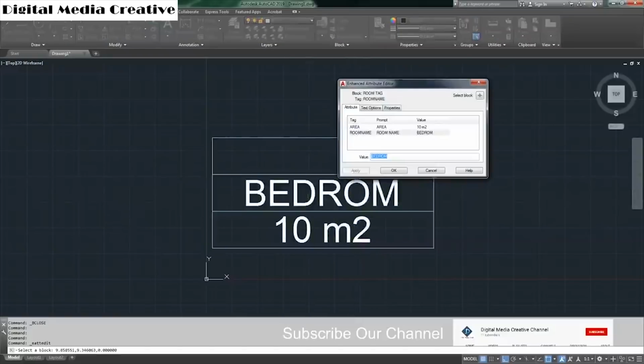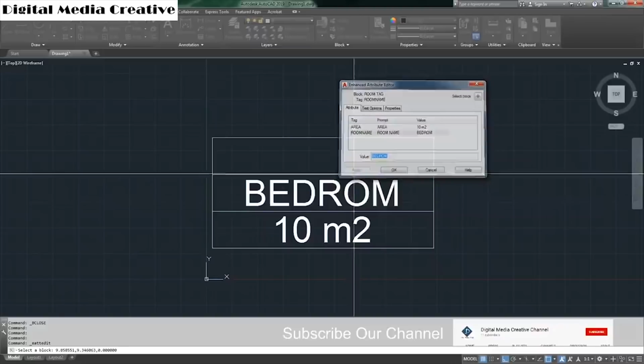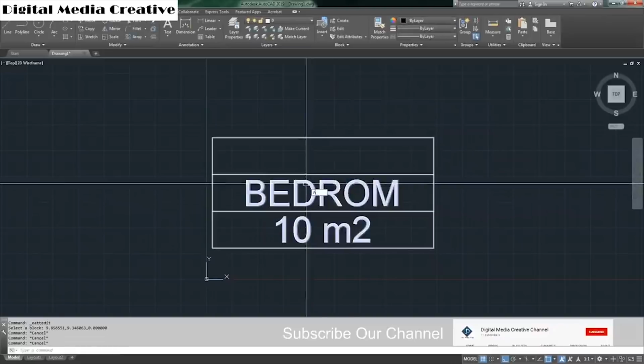Most of the friends ask this same question: whenever we add a new field in the attribute, we cannot see it. Why? It's a simple setting. You can just type ATT-SYNC, that means attribute synchronization. Then you can just enter.